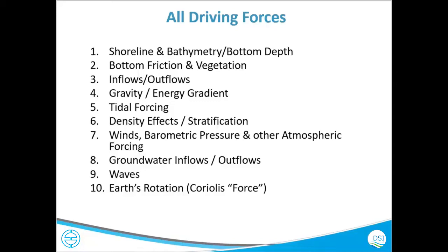And tidal forcing, if you have a system with a tide, coming to the shore and then going back, there will be a lot of impacts. Density, already mentioned it, and winds and atmospheric forcing have a lot of impact on your model. For example, a lake will have a lot of impacts from the winds. The direction the wind is flowing, you'll see the water quality or salinity shifted in that direction. So it's important to have solar radiation, temperature, wind, these all fall under atmospheric forcing.